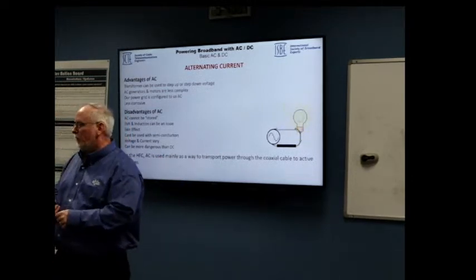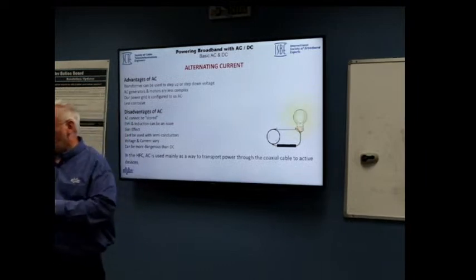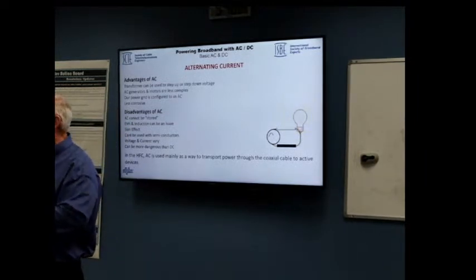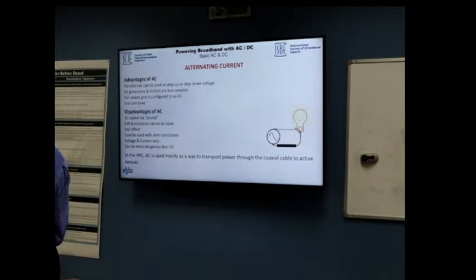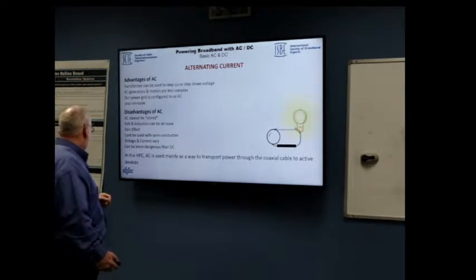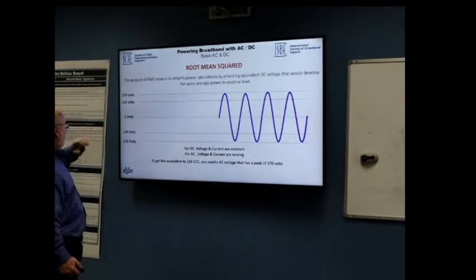We're using an NESC standard, which says that if you send an AC voltage out of less than 90 volts AC, you do not have to have an electrical license to work on it. That's actually the reason we came up with that number, and that's the reason the newer power supplies put out 89. We're getting as much as we can.